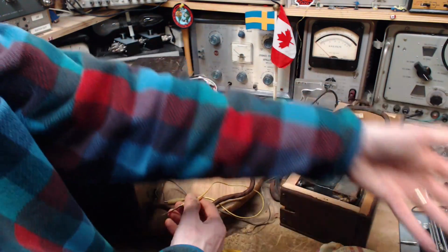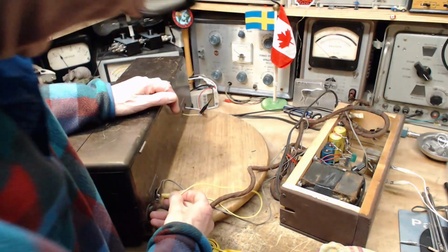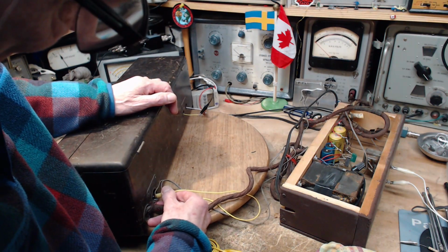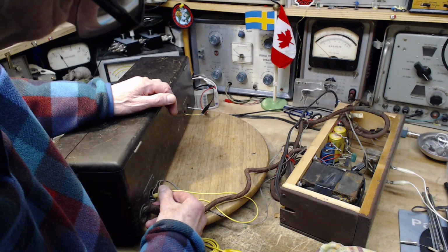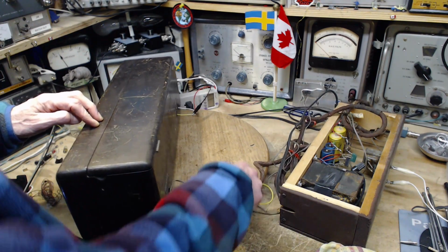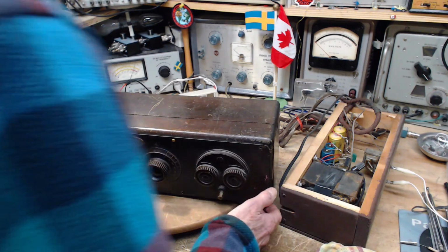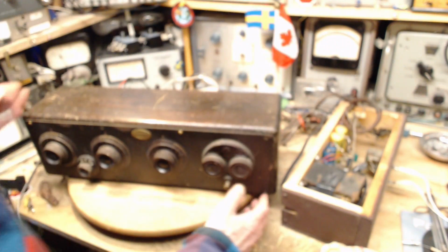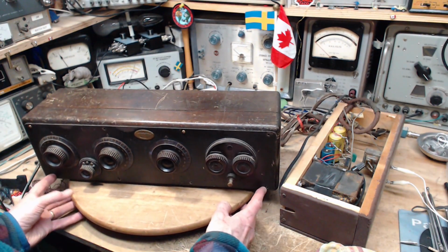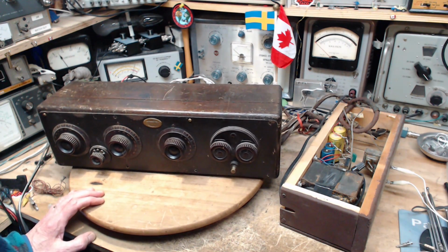We can't let that happen with a regular speaker, so we use an output transformer, which is just barely in there, which you could call an impedance matching device, to match the low impedance of a modern speaker to the high impedance needs of this. Output transformers or audio transformers tend to mess the sound up a fair bit, so they're not the best thing to use, but it is what it is.